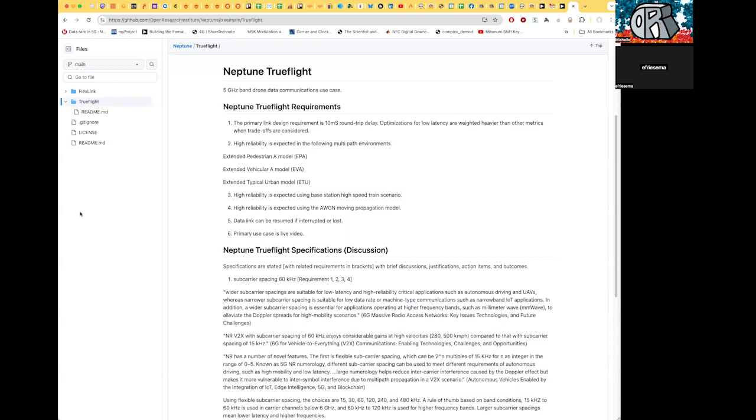If you broadcast from anywhere, it might bounce off a lake, a building, or a cloud, and then you get these weird images that look like your signal, but they're not at the right phase, they're not at the right time, and they become very hard to filter because they're at the same frequency for the most part, barring Doppler shift.